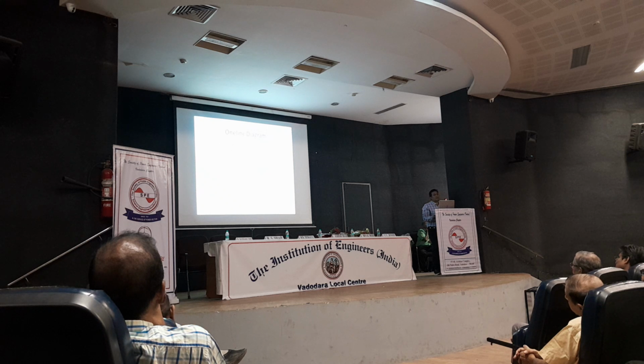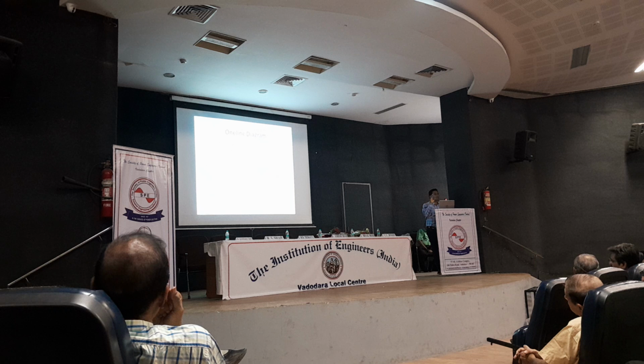And this 0 megawatt and 0 MVAR, if you observe, is nothing but field values. Many times, when you are dealing with MATLAB or other tools, if you want to see the data, you have to take the help of scopes. Here in PowerWorld Simulator, you can display the values in two different ways: one is with field values, one is with a pie chart.